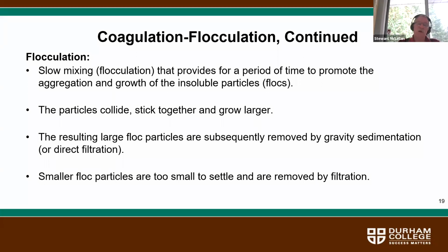In a good system, the clarification process is sufficient to remove your solids to levels where you can easily meet your sewer discharge bylaw limits. In cases where you can't because of residual smaller floc, you will have to go to some form of direct filtration. And facilities I deal with will use sand filters. In some cases, they will use bag filters or string filters to carry out that direct filtration. Okay.